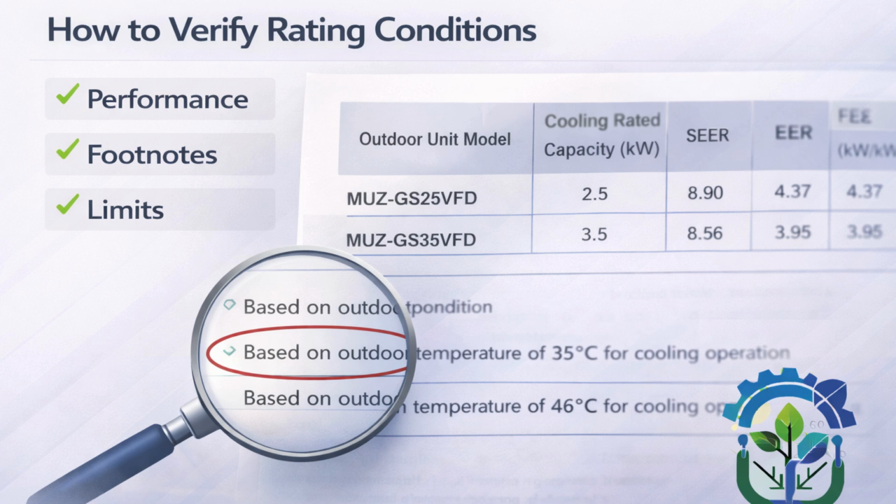Now let's go a little bit deeper and understand how to check whether an HVAC unit is T1, T2 or T3 performance rated in the simplest possible way. Going to step 1, you need to open the manufacturer data sheets from the submittal. Whatever you are reviewing or whatever you have submitted, go to the manufacturer data sheet, look for performance tables, look for cooling capacities, and look for power input.